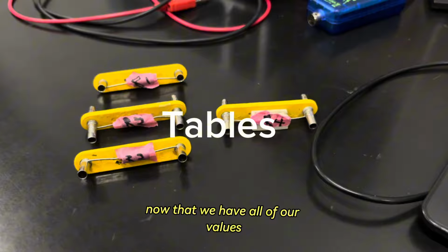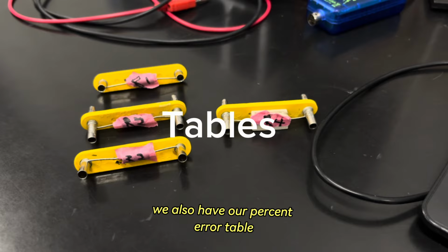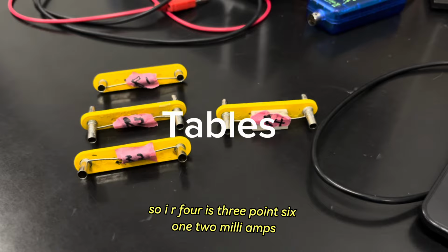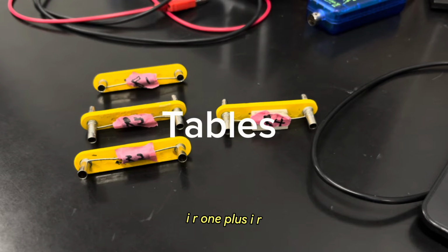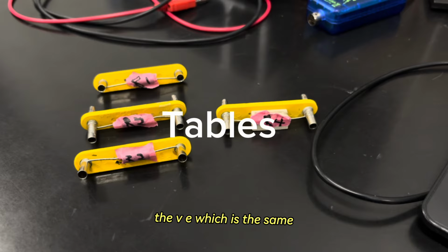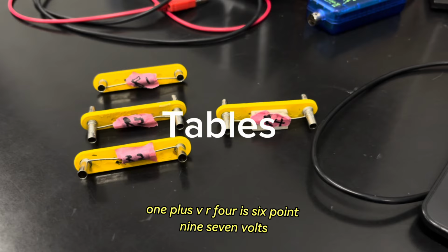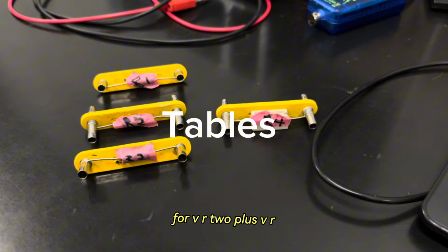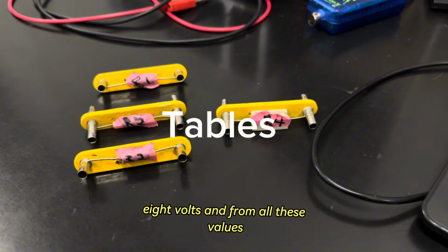Now that we have all of our values, we also have our percent error table. For this, we just had to get our different values. So IR4 is 3.612 milliamps. IR1 plus IR3 is 32.218 milliamps. The VE, which is the same, is 7 volts. Then the VR1 plus VR4 is 6.97 volts. VR1 is 3.87 volts. VR2 plus VR3 is 3.88 volts.